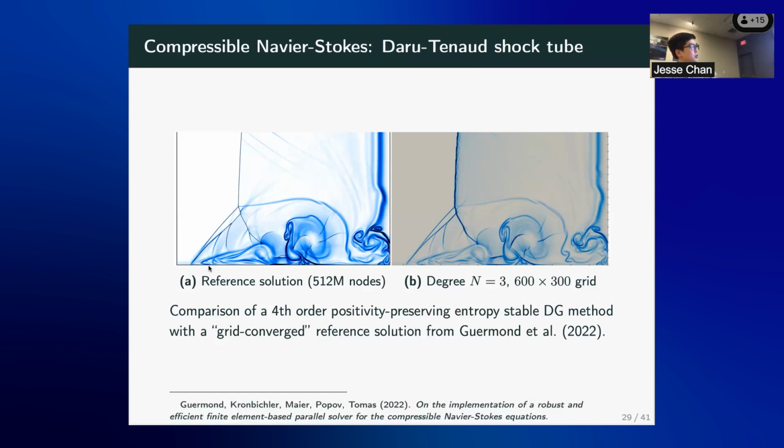And what you actually don't see is that there's a boundary layer. The mesh gets smaller near the boundary to capture these viscous phenomena. So what he shows is that if you take the solution, it doesn't seem to change as you refine the mesh, and neither does the skin friction coefficient along the boundary. That's, I think, the only evidence we have that this might be the right solution, and that it doesn't move as you continue to refine.